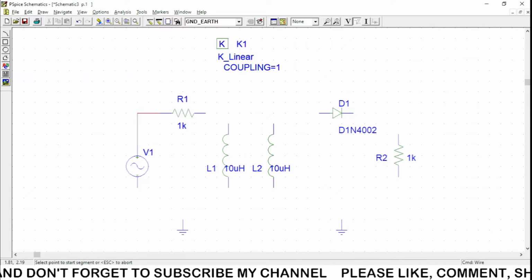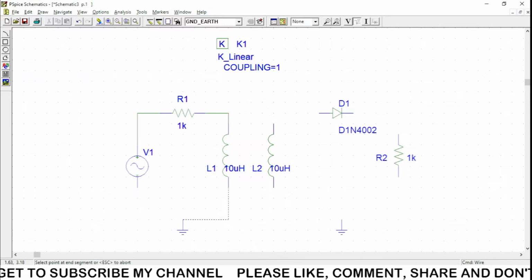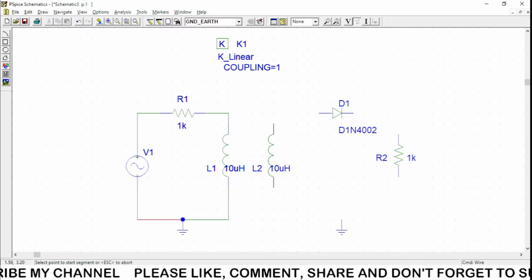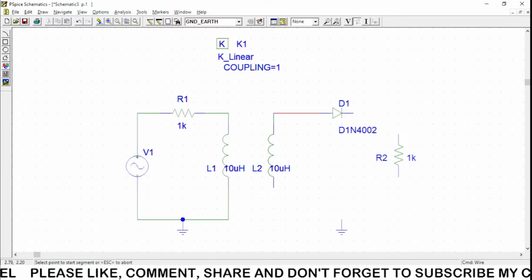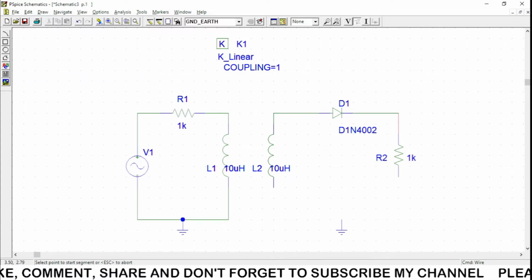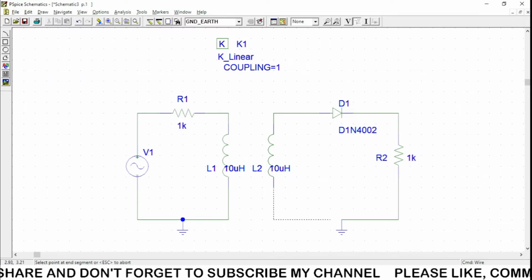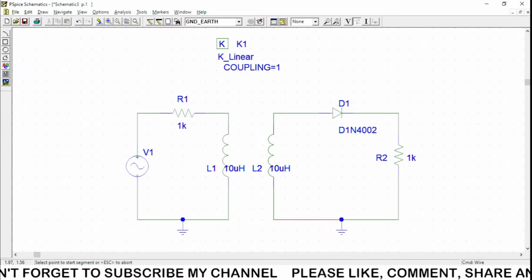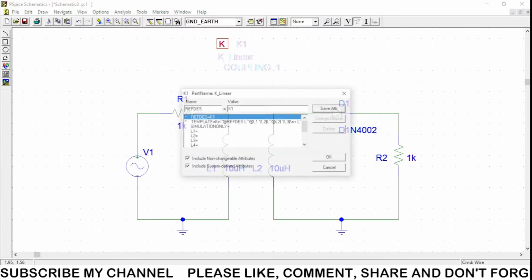I'm joining the V sine source with the resistance R1, inductor L1 to ground, and again this V sine's negative to ground. Then for the mutual inductance concept, this L2 is connected to diode D1's anode. This is connected to resistance R2 and again to the ground. This L2 is again connected to the ground. So how to make this a transformer? We have to click on this K.